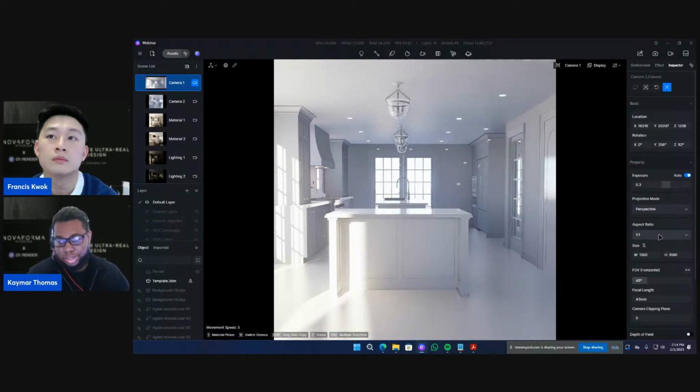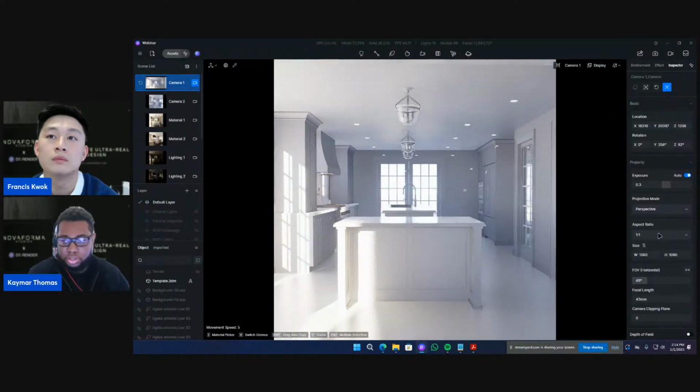The first thing we would do is adjust the aspect ratio. Typically, we do a one-to-one. I preferably like a one-to-one ratio, just because everything is somewhat proportional in terms of what you see from top to bottom and left to right, and you get a focal point that I really like. So we typically do one-to-one, and then we set a field of view with respect to that. I'll cover the different ranges of field of view that we use. Typically, we use a field of view range between 45 and 70 degrees, and I'll show you why we go with that range.